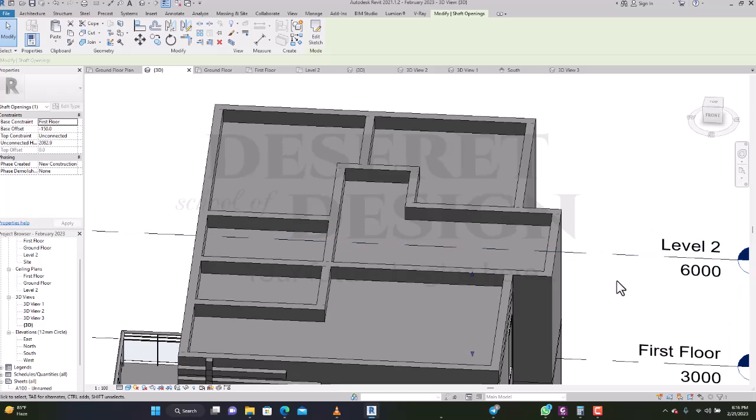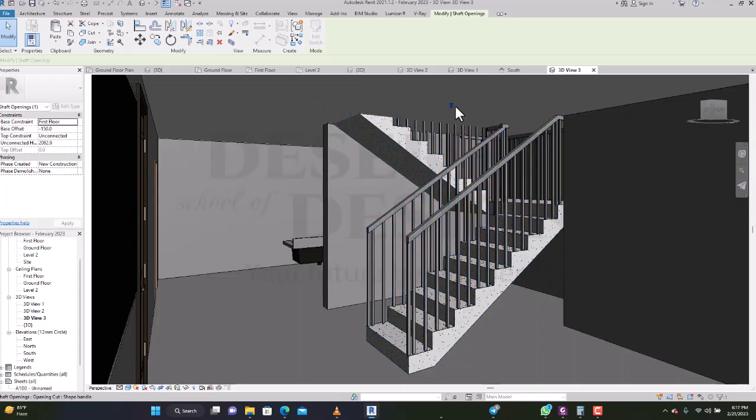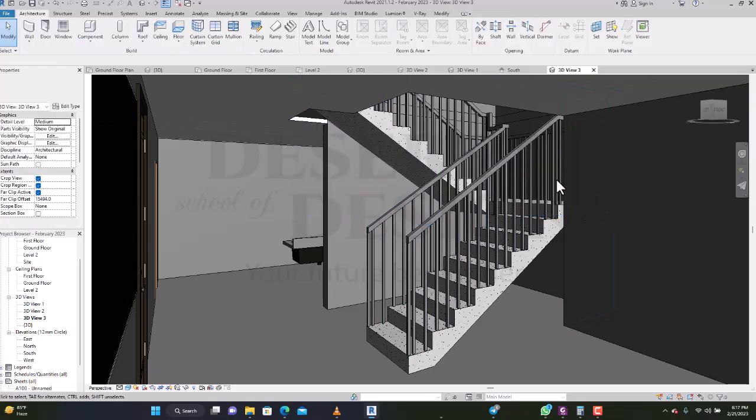So this 3D that you are using? No, I'm just in the 3D to drag. You can be in your elevation, section, anything, so far as you can see your shaft. Now I've done the top. If I go inside the base, the base is still not reaching the floor, so I need to drag the base to a level too. I'll click, then drag it to a level where you see that it will cut open that space.